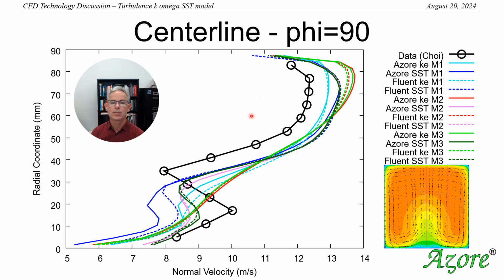Here's the next one, and this one is interesting because at this point we're down here looking at the flow structures, and you can see there begins to be a spread depending on the software package that's being used, but more so depending on the mesh topology. You get a variation in the prediction of what the velocity is in this area.